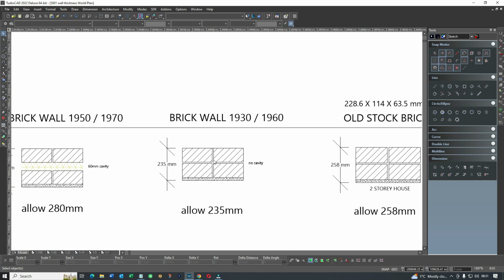All the imperial measurements went out the window and we started going metric. So metric bricks came in around the 70s, early 70s. But before that, imperial bricks. They were roughly the same, 2.5 or 2.6 equates to. They basically did a conversion. They didn't change the size of the brick. They just went from the imperial measurement to the metric size without creating a new brick.